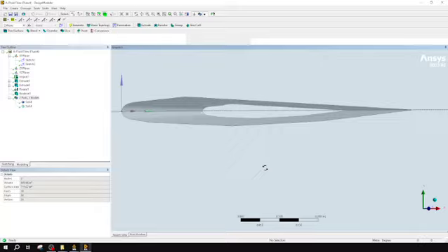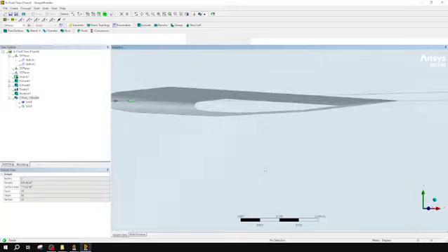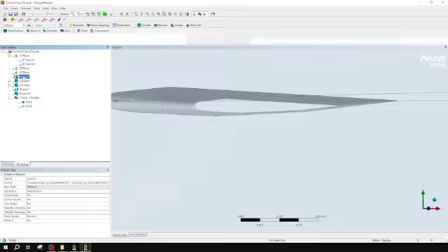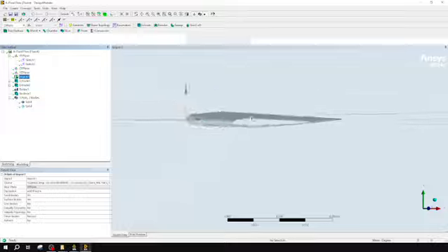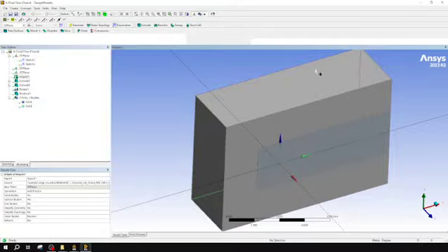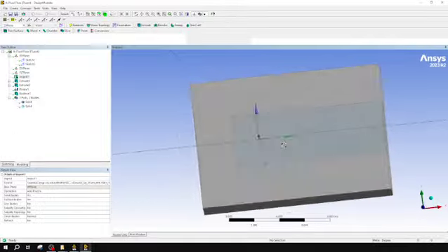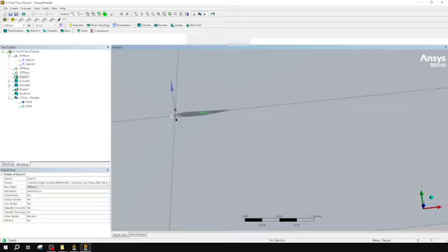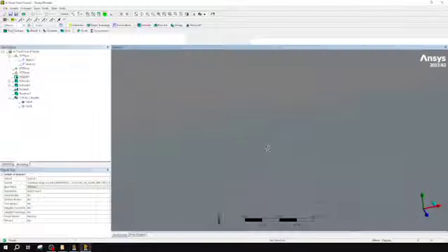I think that's more to do with how it previews this versus the actual geometry that it'll send down the line, but we can easily check that in our next step. So this is all just how you make your domain set up, what my wind tunnel box would be. I've set up this secondary smaller box for mesh refinement. I subtract my desired object from this large body, and I'm ready to move on.